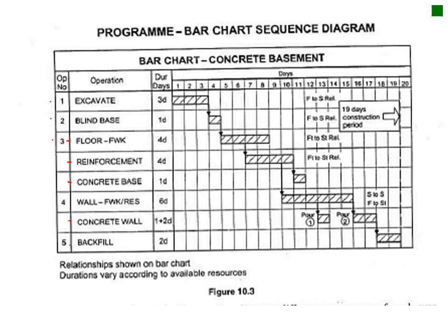And once you've sequenced them, you can allocate time to that, and then you can see, okay, this is more or less how much time you need. You need about 19 days for it, and then you can make adjustments according to your available resources. So maybe looking at your formwork, placing of your formwork, you can maybe put one team on the one wall and another team on the other wall to shorten this period.